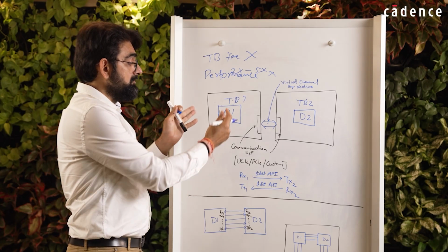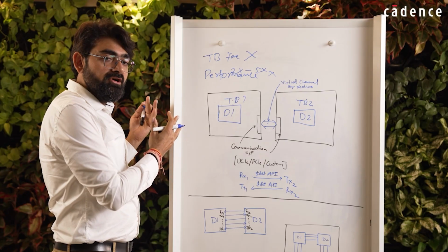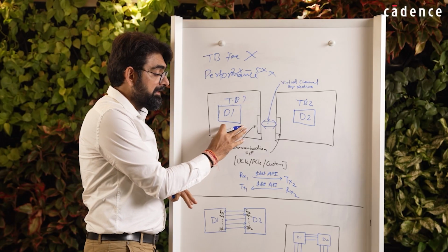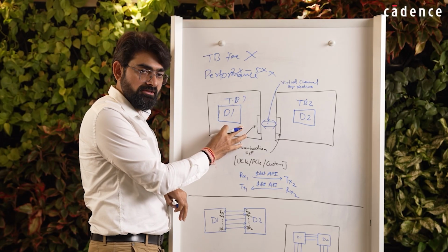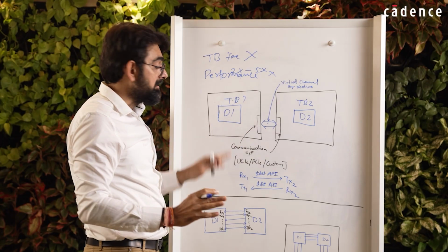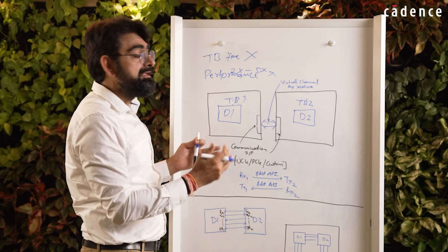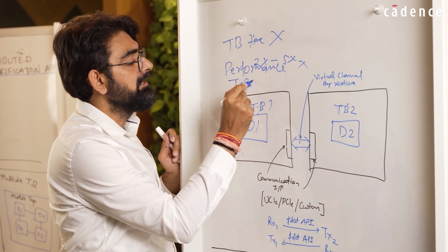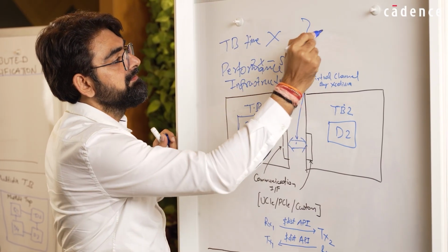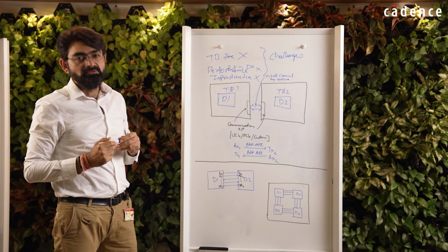And naturally, when you are using this in distributed simulation mode, the weight on your farm, on your infrastructure, gets distributed. What you were already having for a single die verification, the requirement you had with your machine, with the farm that it would run on, remains the same. It does not increase with any number of dies you would like to put into multi-die format. So your infrastructure has no extra load. So your infrastructure challenges, let me put these as challenges, are met with Xcelium Distributed Simulation app.